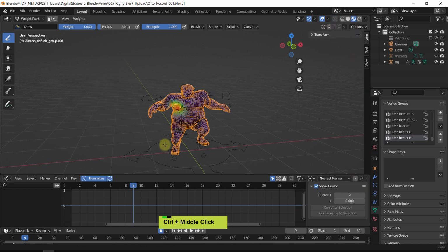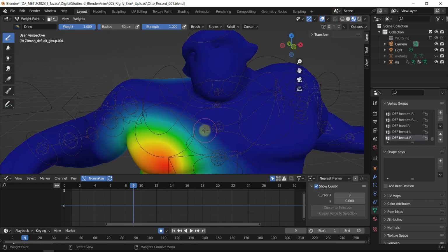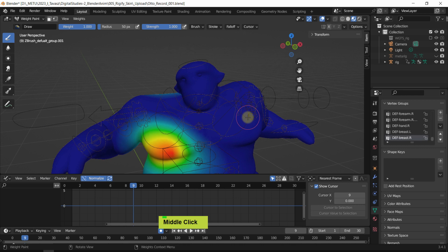And here it's not always handy if we see the wires, so I will just turn this off. Wireframe, turn this off, and this is great. Now, when we are switching to weight mode, it's so generous of the software that we are switching to vertex groups. These vertex groups are named in an odd way. Def means these bones are meant to be deforming the mesh. Every bone will have this extension of def. The naming convention is pretty easy to follow. The only thing that's a little bit unusual is that we have no head bones.